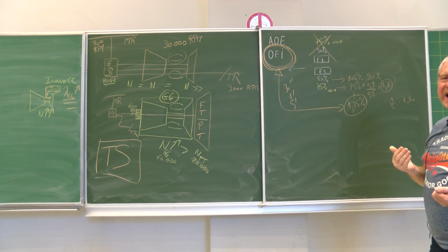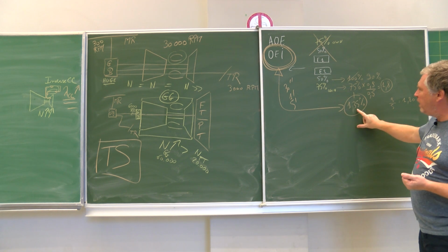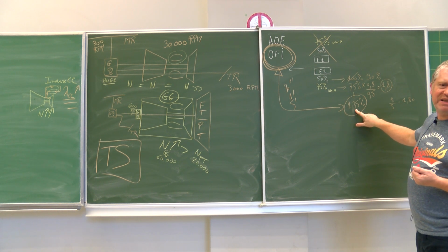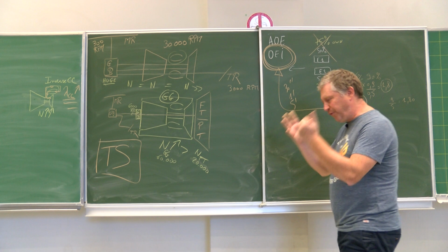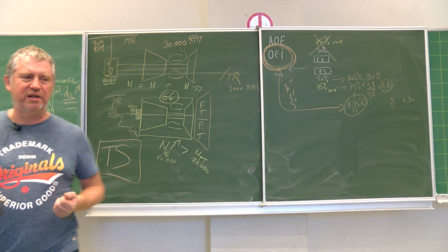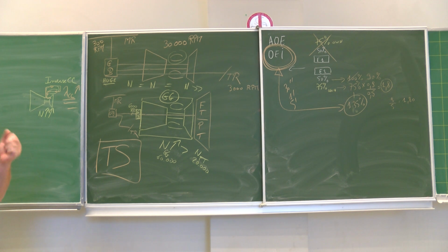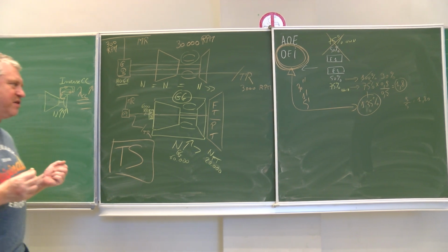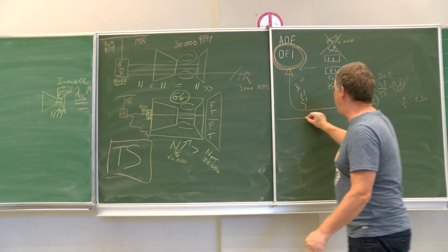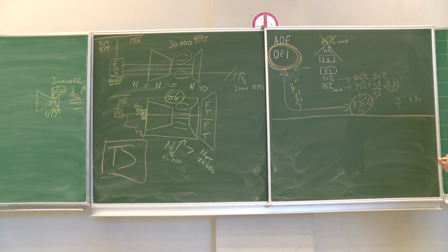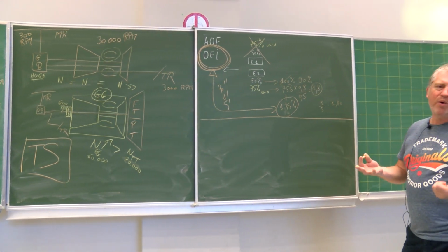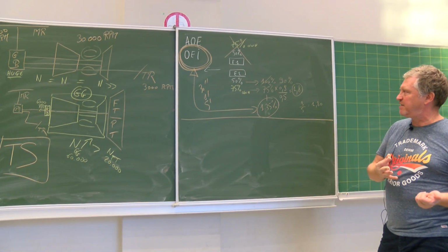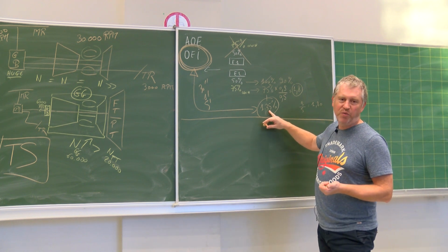But if you are going far away, it's quite possible that you will have a 30-minute OEI. Of course, a 30-minute OEI will not be 135%. It may be 120% or 115%. But this is the philosophy behind this certification of helicopter engines. Very specific for helicopter engines. If you have helicopters with 3 engines, then it's still one engine inoperative, and the 2 other engines are switching to the OEI mode for 2 engines instead of 3 engines, and of course this value will be lower.